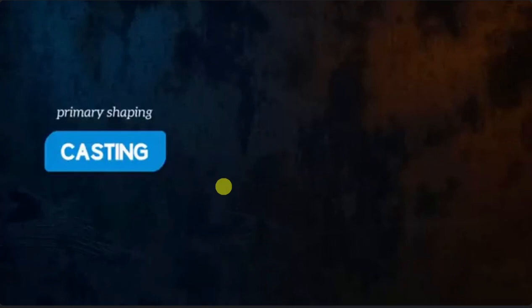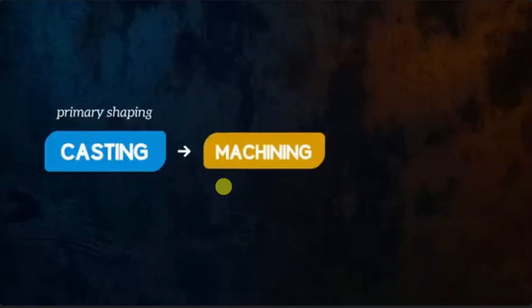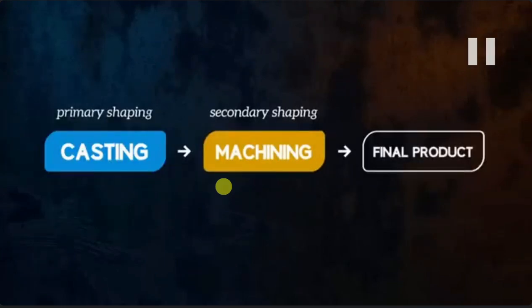A secondary process such as machining is typically needed to achieve the desired surface. In the casting process, the final product is not obtained directly. First we get only a primary shape. Then we take out the casting, and do further processing like machining for finishing. Then finally we get the final product.